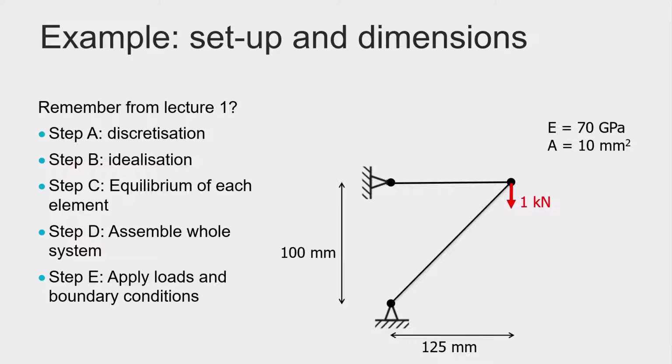Before going into these steps, let's pick a global coordinate system, which is always the very first step to do. And this global coordinate system does not need to be special. We can use the standard XY coordinate system with the x-axis being horizontal, so parallel to the top element, and the y-axis vertical, so the load is in y direction.